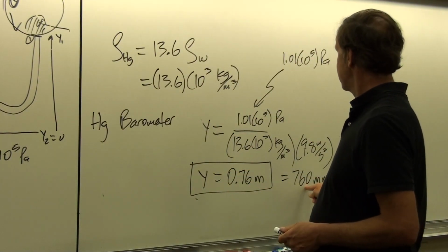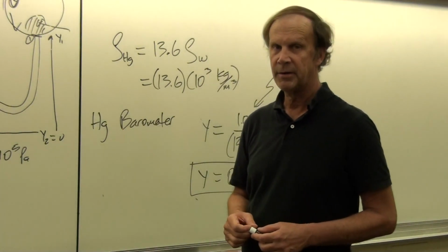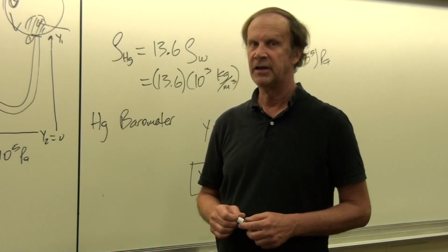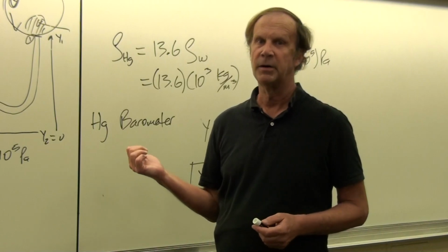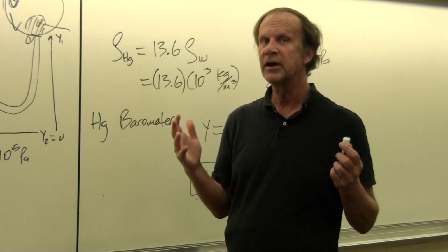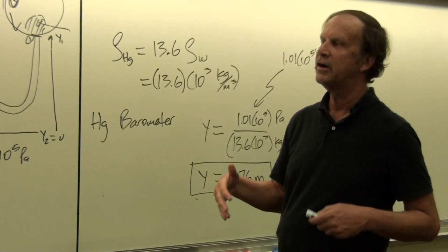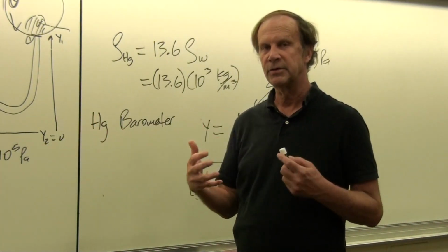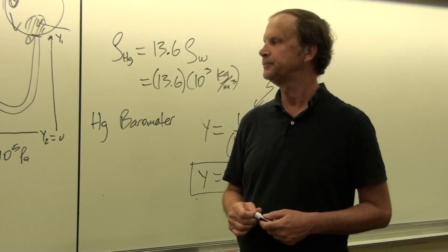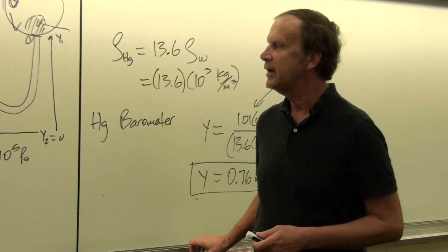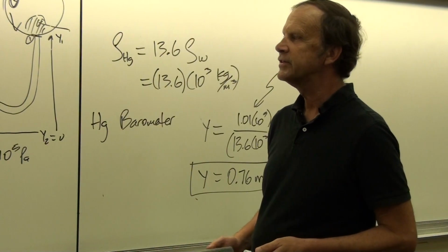But it turns out that the 760 measurement is often used in a sphygmomanometer, which is a blood pressure machine. And so when you say that you've got a blood pressure of 120/80, you're talking about millimeters of mercury. So it's important that we do have some familiarity with PSI and millimeters of mercury, even though normally in a problem like this, we would be solving for it in terms of the number of pascals. Okay, so that takes care of atmospheric pressure if the fluid is not moving.